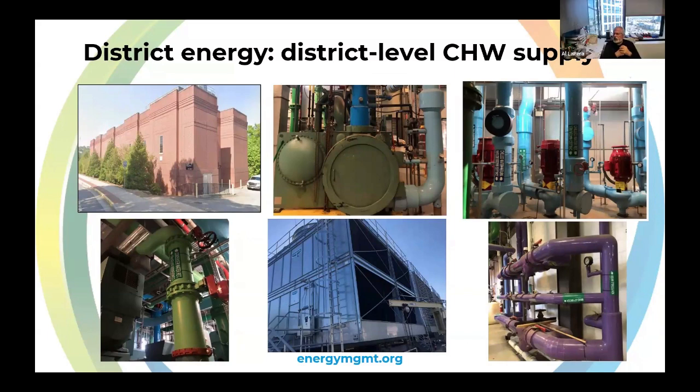So we have five distinct loops, and of those loops, two have significantly large plants which anchor them. Top left there is our Depth 1, which anchors our central campus chilled water loop, and in there we've got 4 chillers with 6,000 tons between them. They're interconnected, with cooling towers on top, so that will anchor most of the central loop.